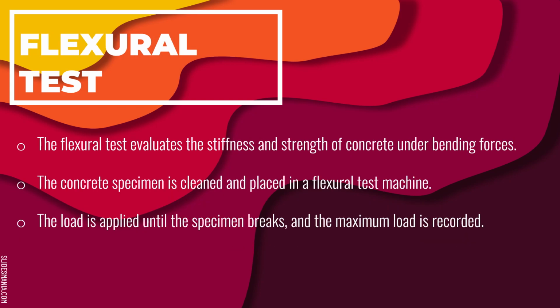Then, flexural test. The concrete specimen was taken out and the surface was wiped of any grit or projecting fins of the cube that will be in contact with the platen. The dimensions and the weight of the specimen was determined and recorded. The specimen was placed in the testing machine and it was ensured that the surface of the testing machine was clean. The specimen was placed centrally on the testing machine and it was ensured that the height of the machine to the specimen was not too far. The data of the specimen was filled in the software of the machine in the computer.